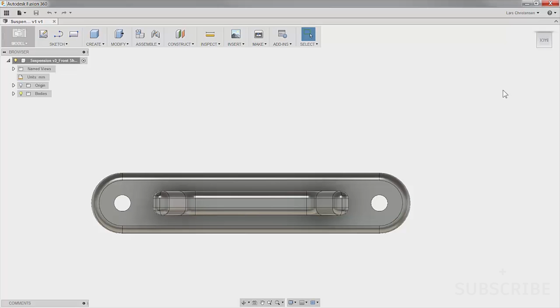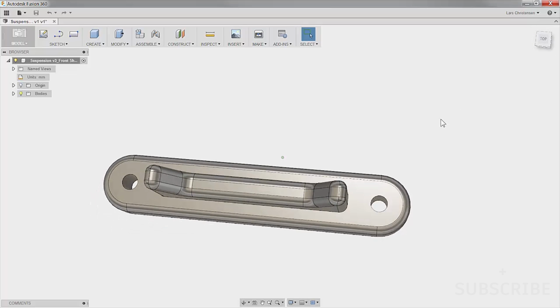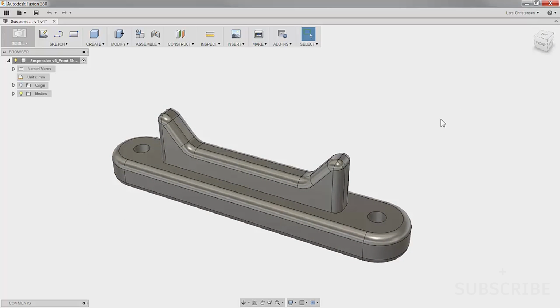Well, it's extremely easy to change that inside of Fusion. All you're going to do is place it to the view where you want the model. So in this case, I want this to be top. Go up and right click and then go down and set current view as top. And just like that you can see up there, now this is the top that I wanted. So really all we did was change the camera position of the way we look at the model. Super handy.